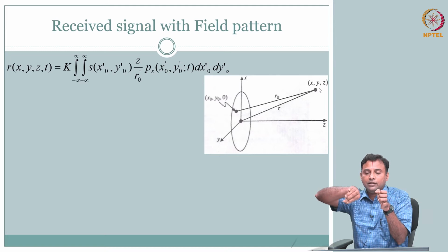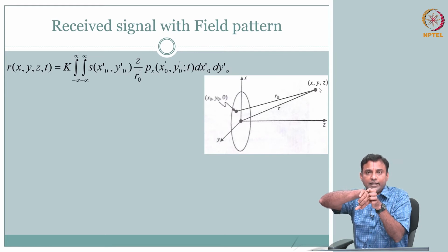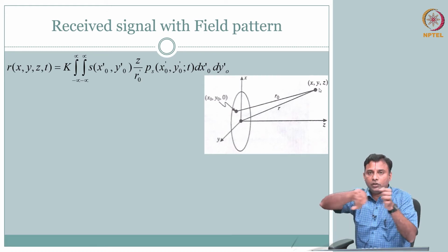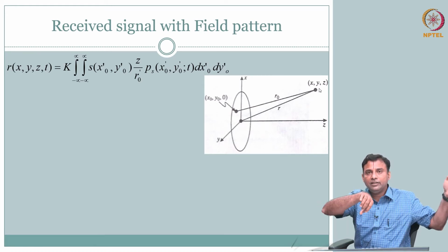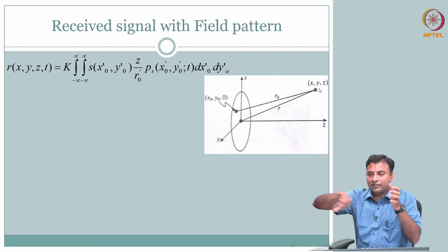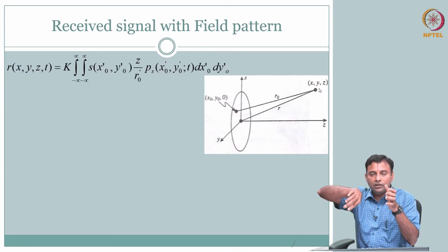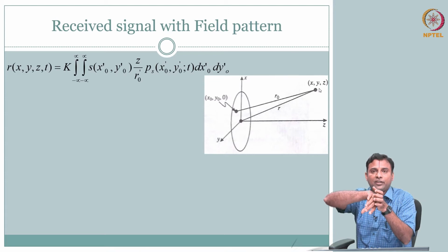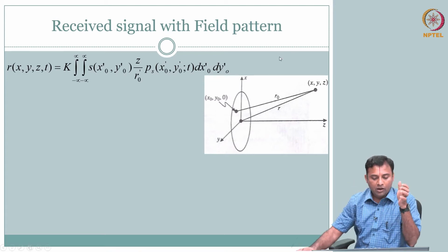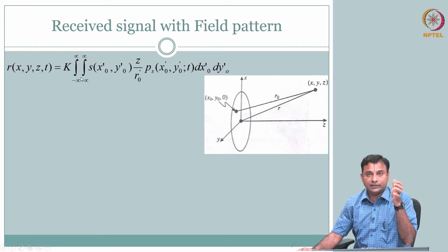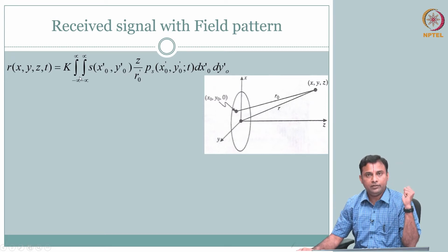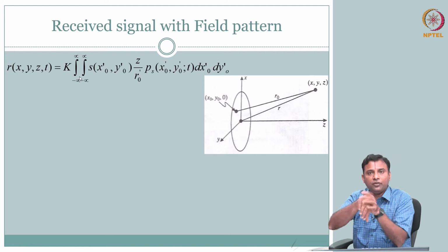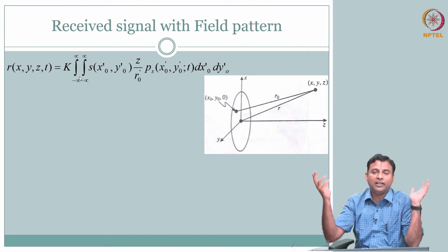So when the spherical wave is travelling and hits the crystal back on the receive side, it is going to oscillate and then convert to electrical. So this is going to oscillate, right, pressure wave. Whatever this spherical wave that is coming out, wherever it is hitting the surface of the crystal, all of the excitations in the crystal in the reverse are going to be summed, contributed. If it is not falling on the detector, that wave just went somewhere, we do not care about it.